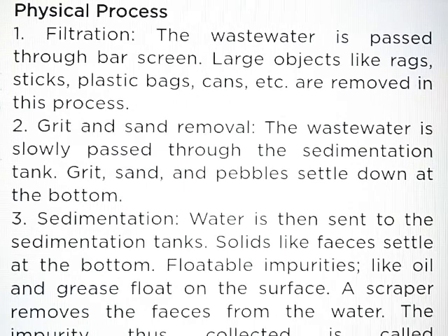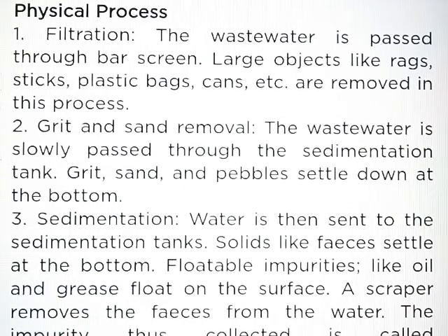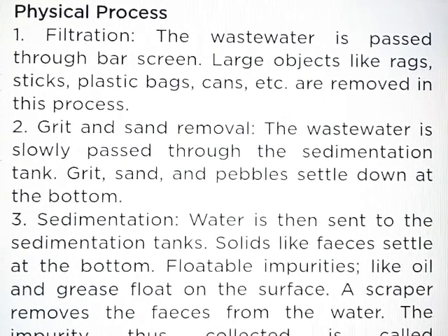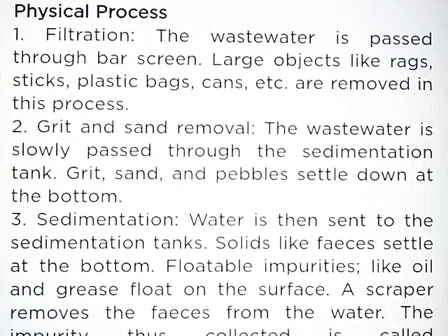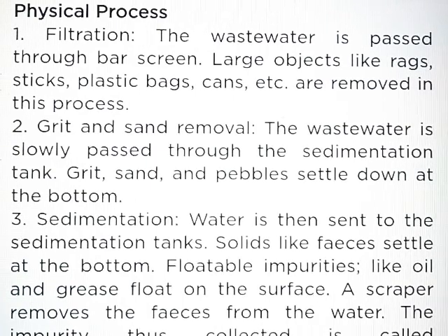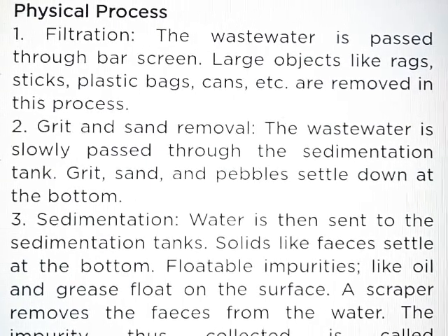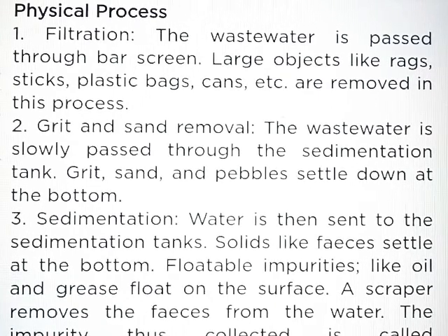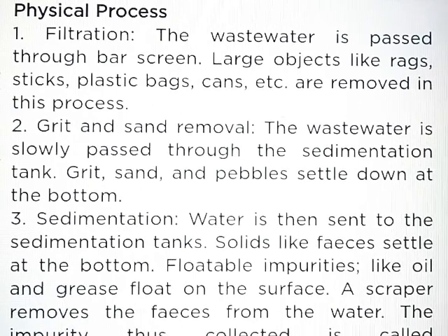Physical process. First, filtration. The wastewater is passed through bar screens. Large objects like rags, sticks, plastic bags, cans, etc. are removed in this process. Second, grit and sand removal. The wastewater is slowly passed through the sedimentation tank. Grit, sand and pebbles settle down at the bottom.